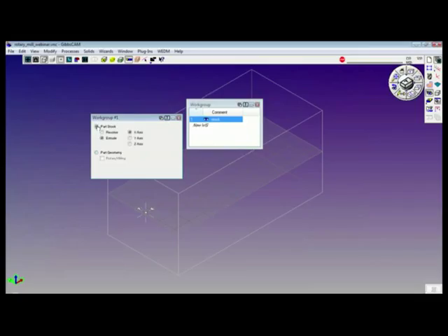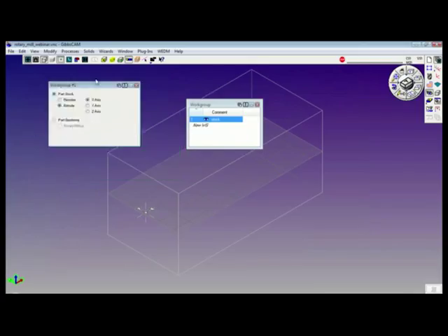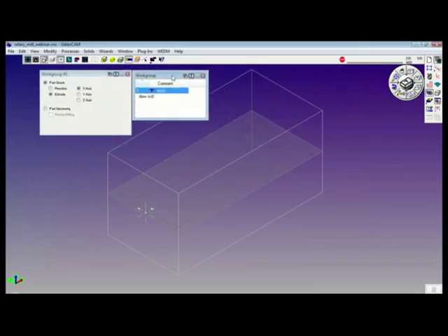Part stock allows me to define my geometry as either a revolved shape or an extruded shape along a given axis. In this case, I am going to define a 3-inch diameter piece of stock. To do so, all I have to do is create a circle at the origin of my work group. I'm going to open my geometry creation palette, open the circle creation tile,